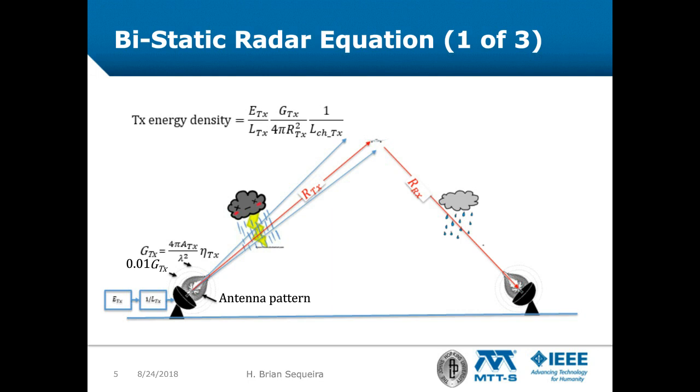The antenna pattern has a main lobe of finite width about the peak and auxiliary lobes, known as side lobes, in other directions. For the antenna pattern shown here, the gain of the auxiliary lobes is 1% or less than that of the main lobe, because each of the faint concentric circles represents 20 dB reduction in gain in this polar representation. Nevertheless, the integrated energy over all the side lobes does not illuminate the target and therefore represents